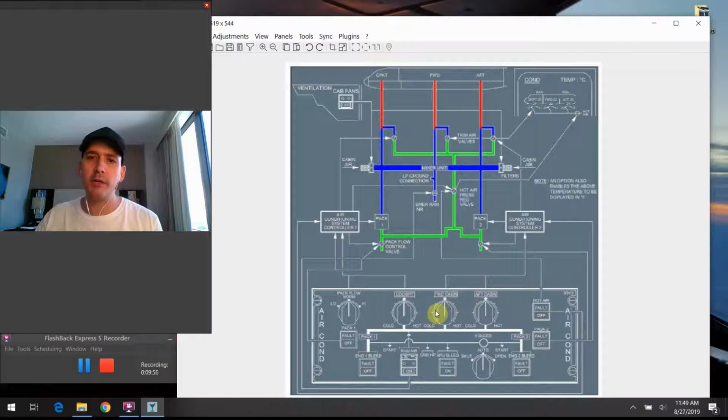point on these knobs over here, it's just going to command the packs to output the same temperature across the system. And then theoretically the environment inside will just mix up the air, and it's going to naturally circulate, just the way it does. And you of course have this basic mode of cooling.